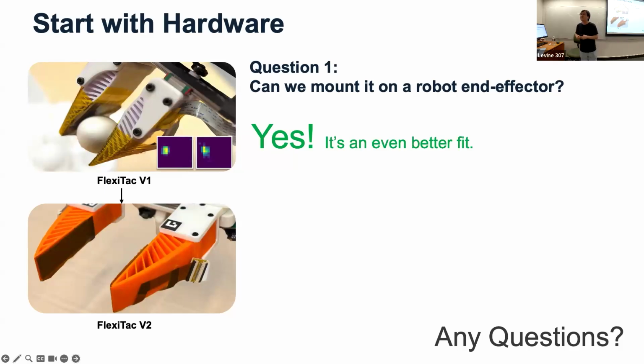What about drift and lifetime? I know regular FSRs have drift over time, and the longer they're used, the more they may degrade. The curvature of the force versus resistance changes, the slope changes. You mean the piezoresistive material has features where the force-to-reading relation is non-linear? Yes, non-linear.